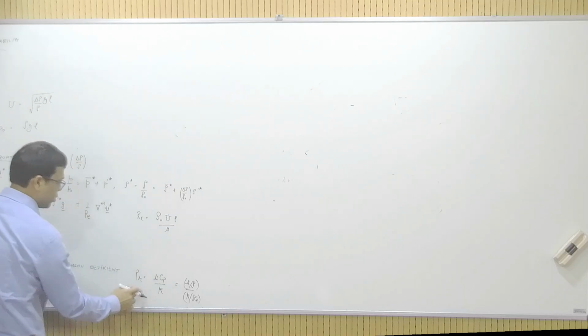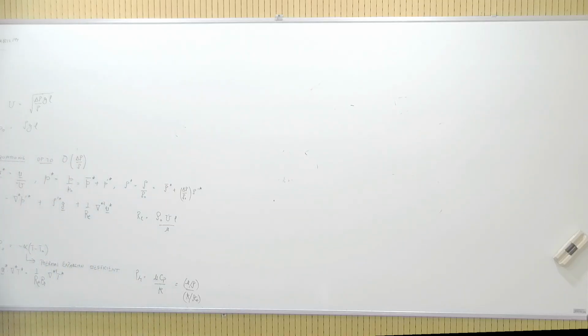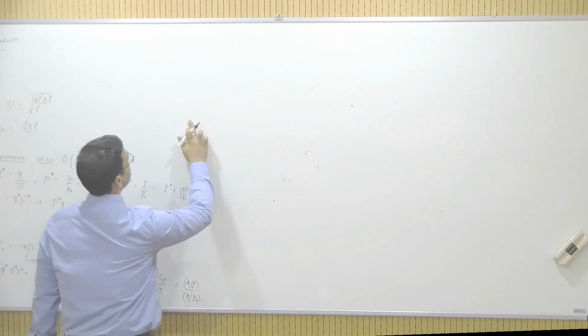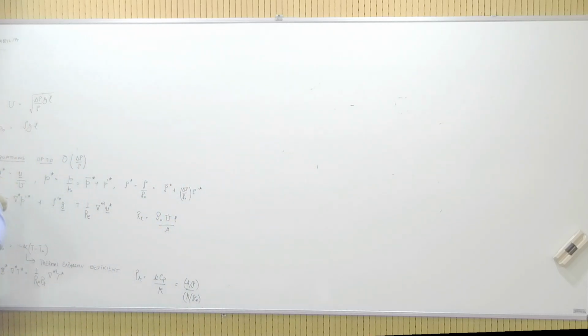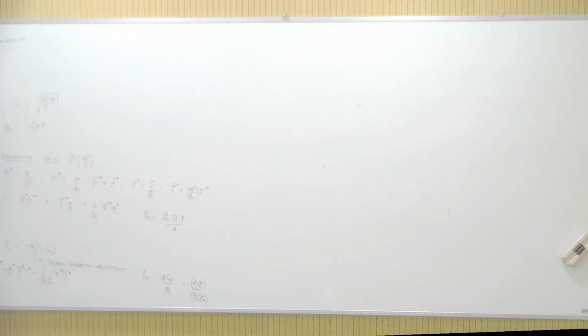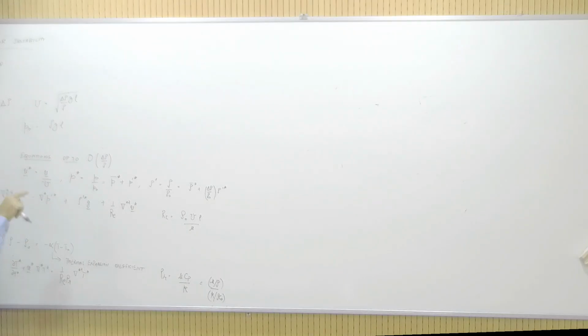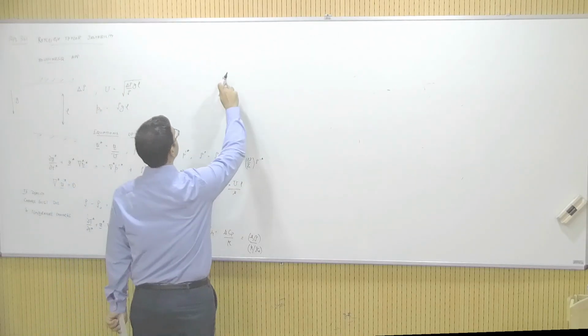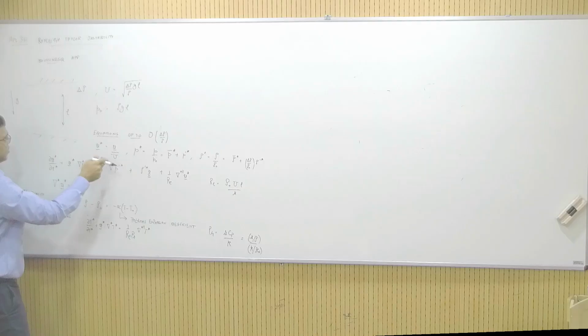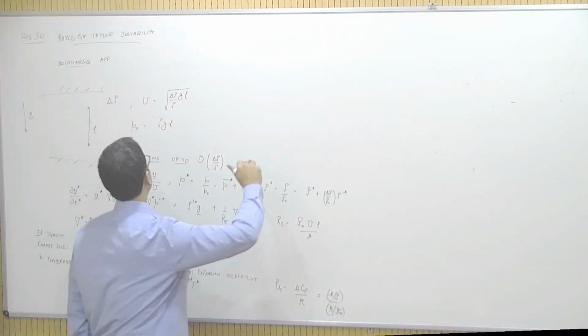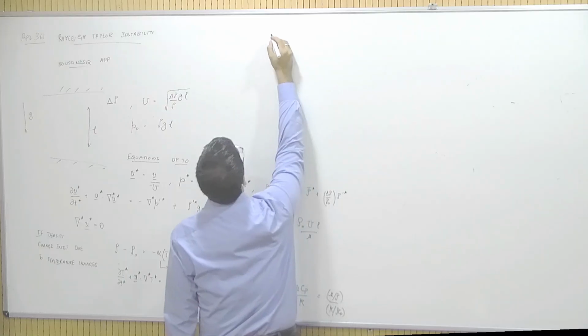Okay, so that's what Prandtl number is, and this is what our non-dimensional equations look like. For the sake of this problem, I am going to substitute the scales back and convert it into a dimensional form. Because when we are looking at an instability, you will see that we have to non-dimensionalize using slightly different scales. So substituting the dimensional variables back, what you will see is that the equation is simply